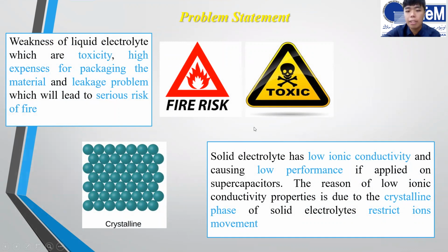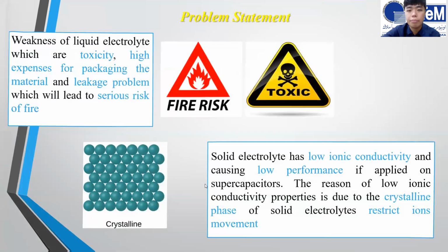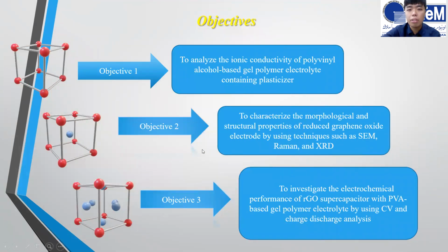The second problem statement is that solid electrolyte has low ionic conductivity, causing low performance if applied on supercapacitors. The reason for the low ionic conductivity is that the crystalline phase of solid electrolytes restricts ion movements. Next, there are 3 objectives for this project. Objective 1, to analyze the ionic conductivity of polyvinyl alcohol-based gel polymer electrolyte containing plasticizer.